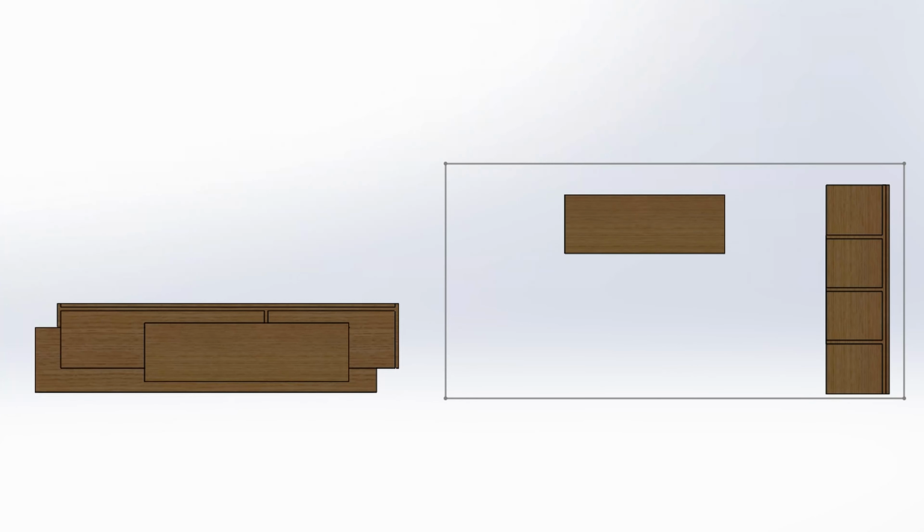One of the biggest advantages to CAD, in my opinion, beyond being able to design everything, is being able to nest your parts. This means taking all of your pieces and laying them out flat on whatever size material you have, ensuring that you get the most parts out of every sheet and don't end up with any awkward remnants. You could take a project that would have taken 7, 8, or 9 sheets and reduce it down to 6 sheets, maximizing your utilization and ensuring that the cost of the project drops and that you get the most out of your material.